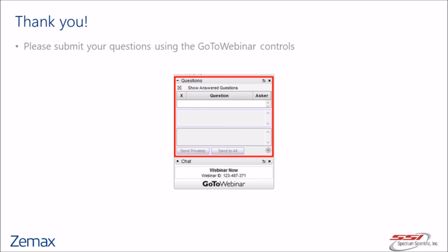In theory, you could control this by measuring the slope on a part with high enough resolution. For example, we have an operand that measures the slope. You could set up a measurement of a grid across the part that's high enough to capture any mid-spatial frequencies that you're worried about. If you were doing, for example, diamond turning and there was a specific frequency that you were worried about, you could sample the surface specifically at that frequency.